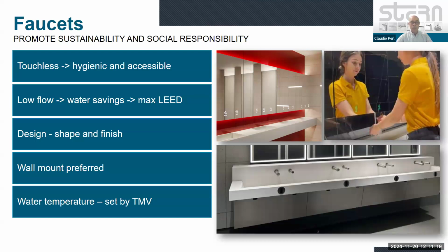Also, low-flow aerators allow this technology to be in compliance with LEED requirements, maximizing LEED points. Design, shape, and finish: it involves different types of finishes and aesthetics in commercial applications. Wall-mounted preferred, and water temperature, with a thermostatic mixing valve if needed.